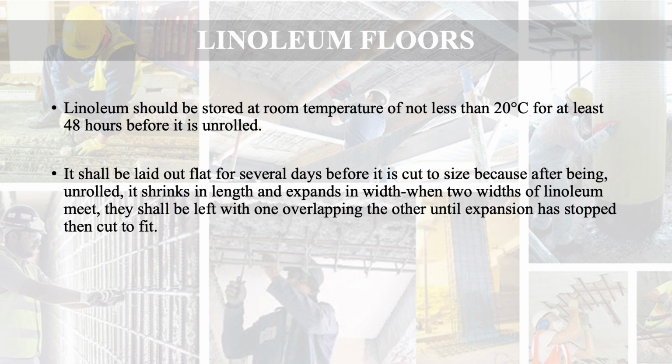It shall be laid out flat for several days before it is cut to size, because it has a very peculiar property that after being unrolled, it shrinks in length and expands in width. When two widths of linoleum meet, they shall be left with one overlapping the other until expansion has stopped, then cut to the size.